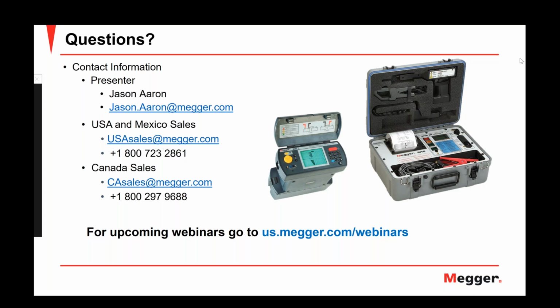So if you're talking about vented batteries where you have access to the electrolyte, the best way to get the temperature of the cell, or of the different cells if you are averaging the value, which is the recommendation, is to measure the temperature directly on the electrolyte. Any digital hydrometer that does that will give you that information. That will be the best thing to do.